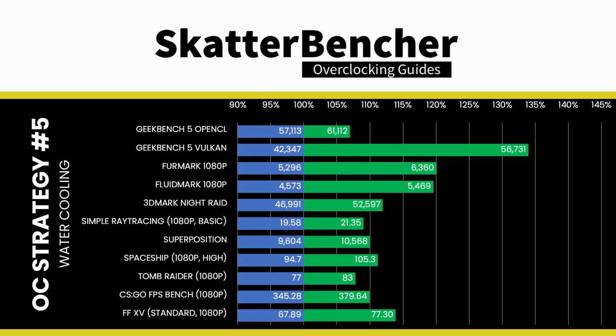We used the same settings as our previous overclocking strategy as, well, all the sliders were already maxed out anyway. We ran the benchmarks and checked the performance increase compared to the default operation. The main benefit of adding water cooling is the significantly improved temperatures. During a FurMark stress test, the GPU and GPU hotspot temperature decreased by 8.5 and 20 degrees Celsius respectively.